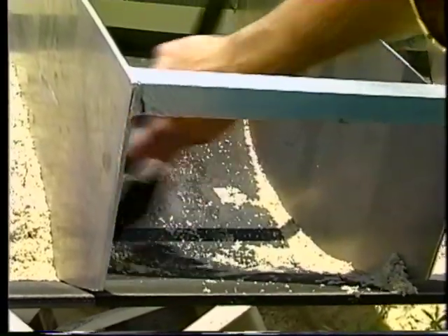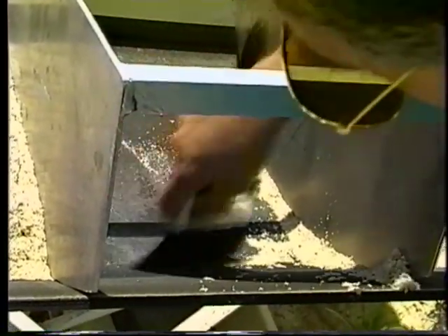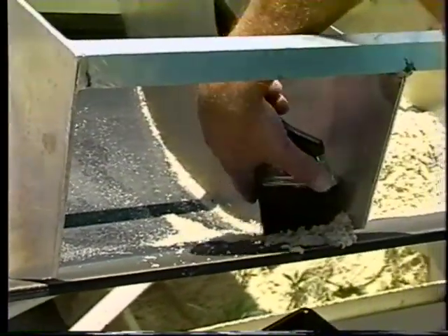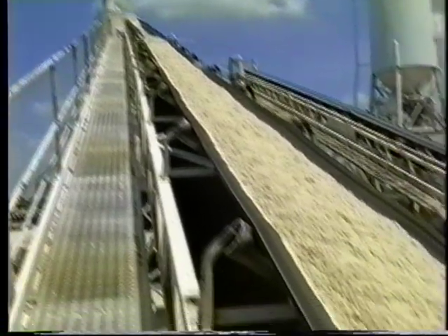The cross-section of the template must match that of the belt. If the template does not match the cross-section of the belt, gaps between the belt and template will be visible when material is removed from the belt. Material underneath the template also indicates that the template does not fit the belt.